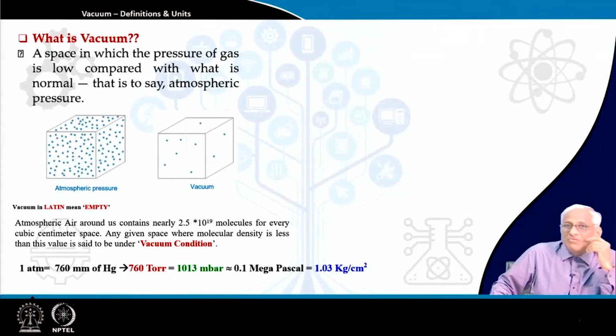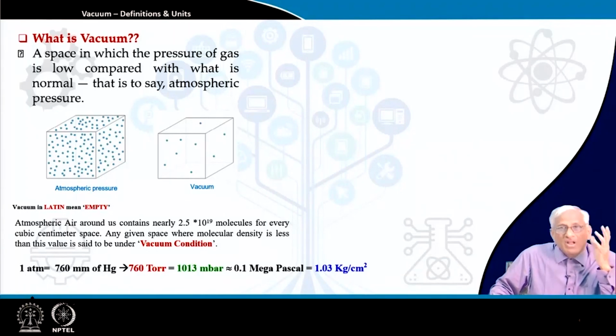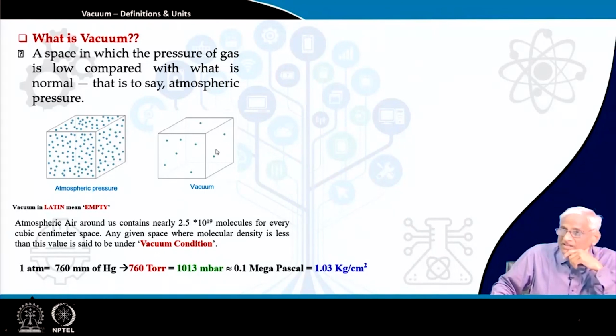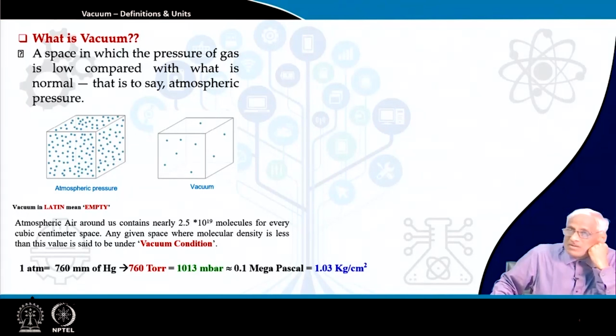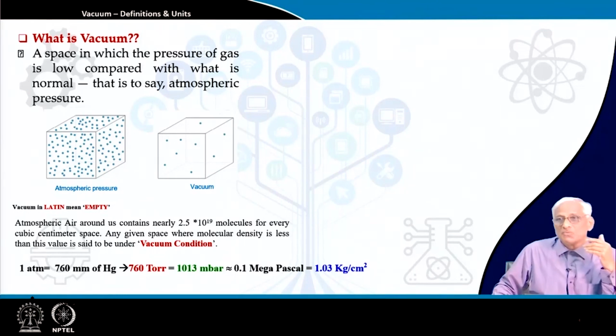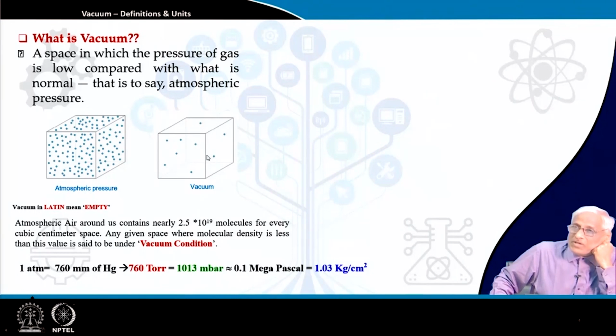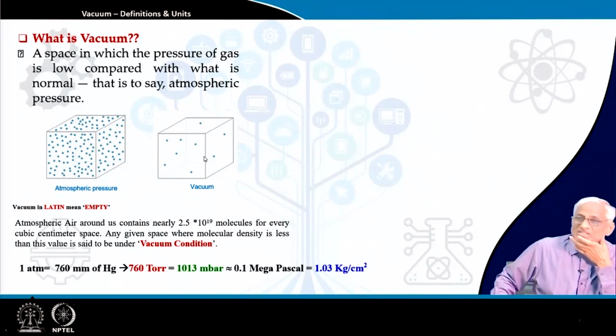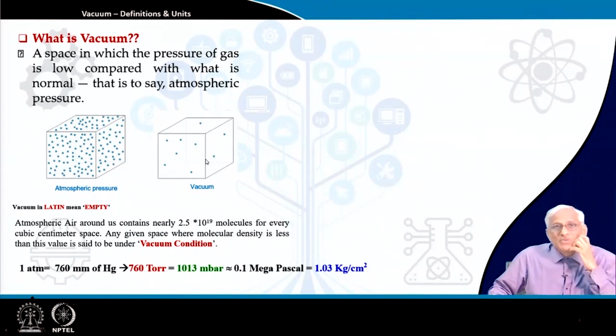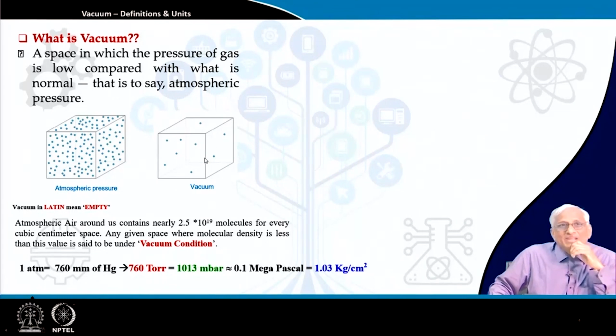So, all the fluid mechanics concepts like viscosity and Navier-Stokes equations are valid, but when it comes to high vacuum conditions, these concepts are not valid. That means you cannot use computational fluid dynamics for high vacuum applications. You have to introduce a new dimension called molecular fluid dynamics, MFD type, not CFD. These things we will come to in detail later.